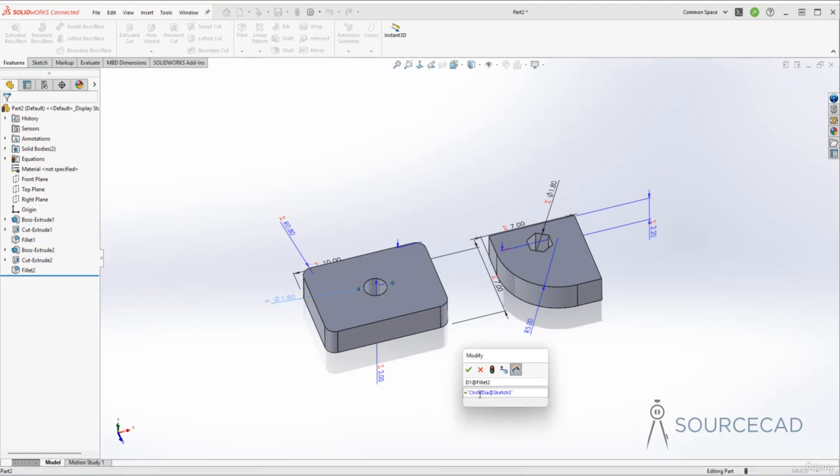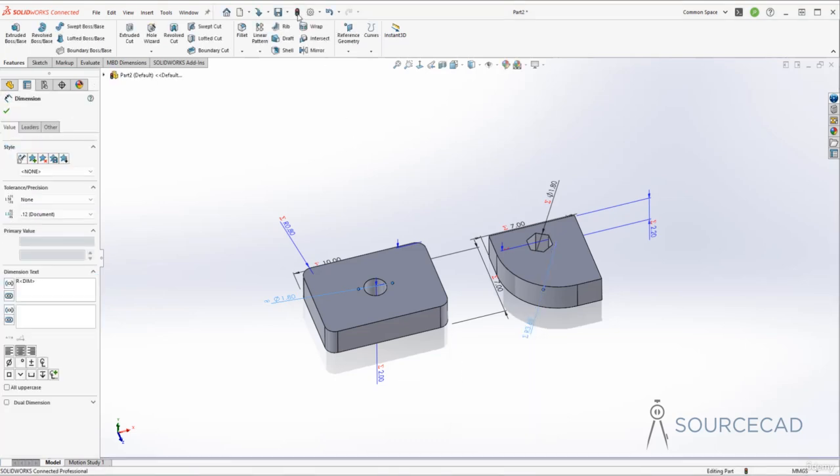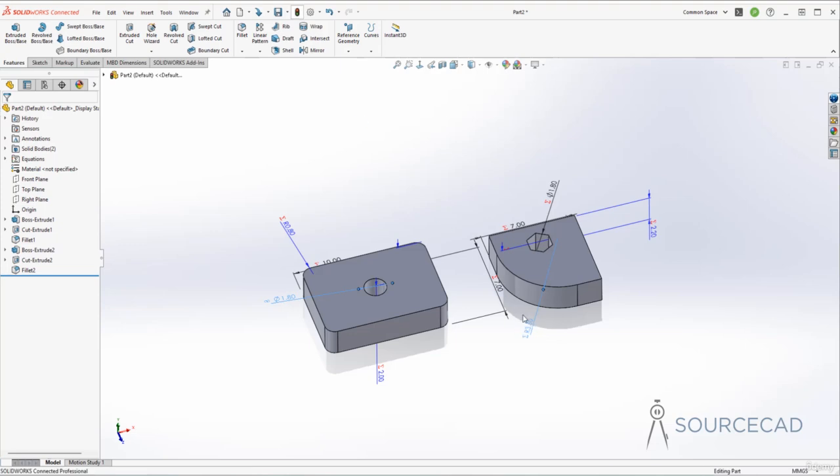So circle dia, that's the global variable, the linked one, which is selected, and let's say multiplied by 2. That's what we want. So it will automatically calculate the value, whatever the value is, and it's going to apply that value for its radius. So just click OK and rebuild this. And here we are. So it is 3.6. So it just calculated the final value and it will show it here.